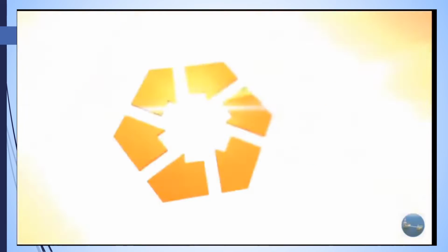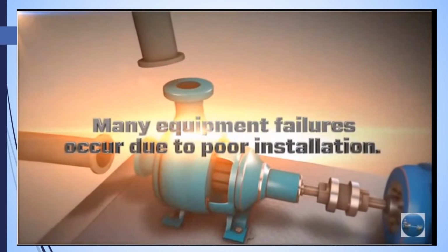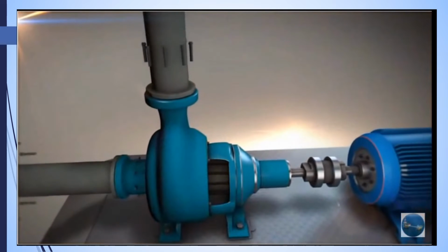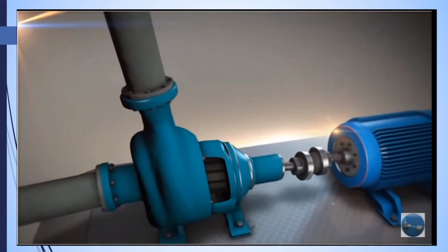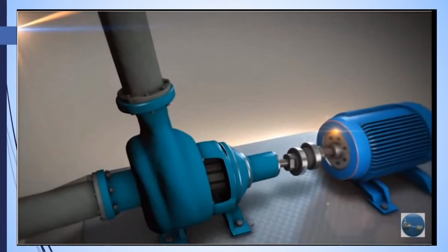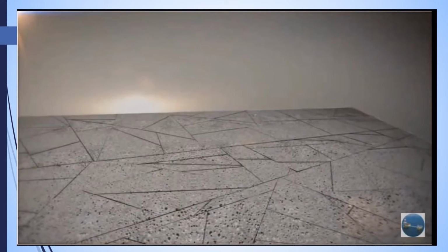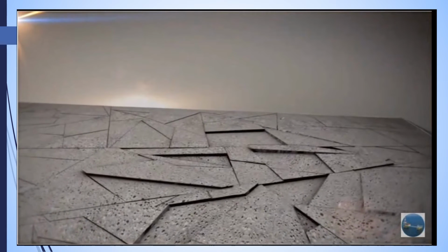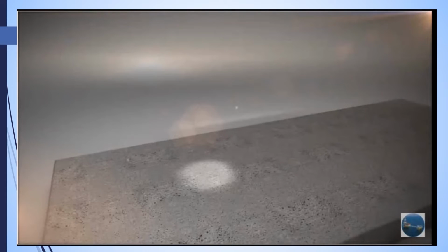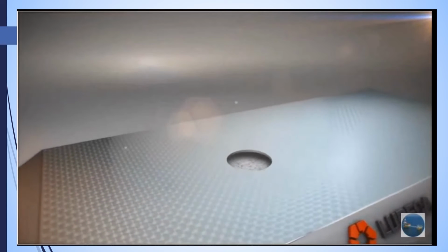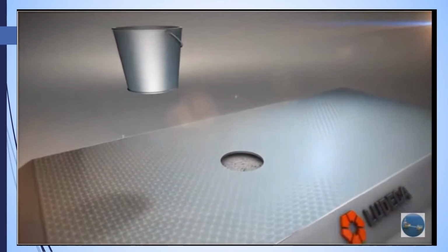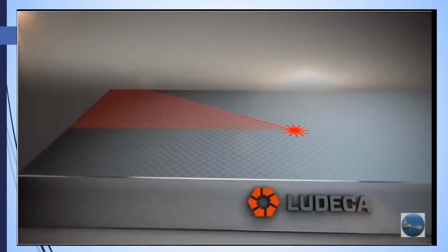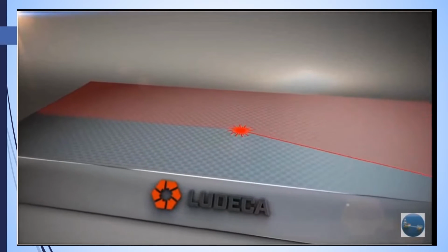Shaft alignment know-how. Installation. Many equipment failures occur during what is called the infant mortality period. In other words, soon after machines are first put in service and are typically due to poor installation. The foundation must be able to withstand the mass of the equipment and any operational load stresses and vibration that the machines will generate. Once we ensure that it is well prepared, flat and level, we can mount the base plate upon it and properly bolted or grouted to the foundation and ensure that it too is flat and level.